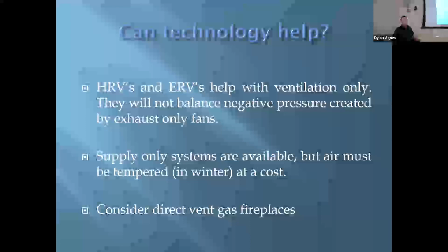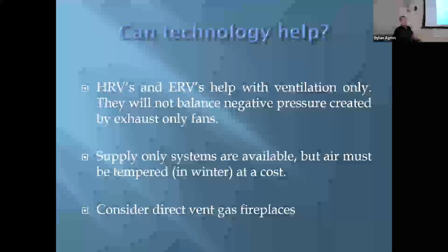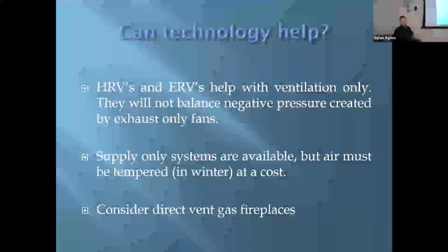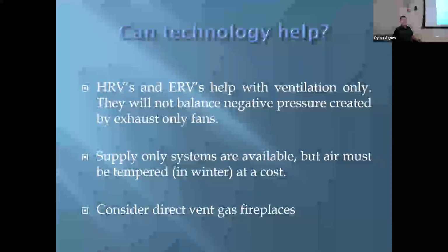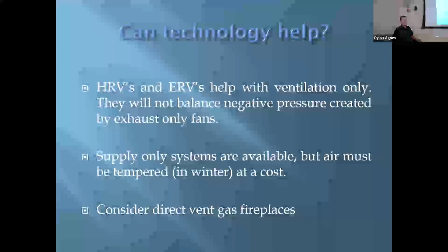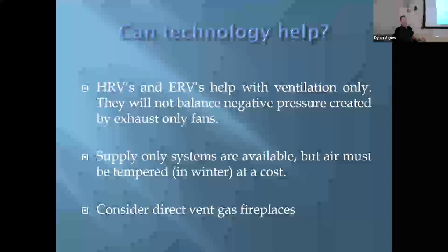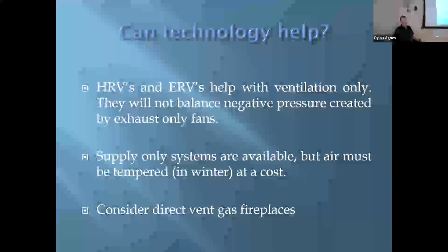They do have supply only systems. Unfortunately, this has been the solution on a few homes where we had to go in and put a supply only furnace into it. It brings in all of its air from outside and reheats it for the inside. This is where the energy efficiency comes in, because now all we're doing is heating air to be drafted out to go up a hot chimney to go out and heat the world. It can get costly.